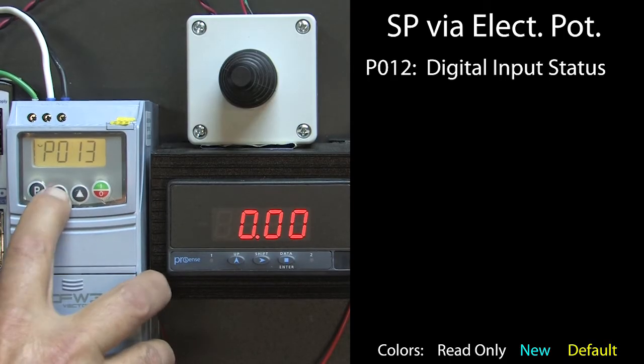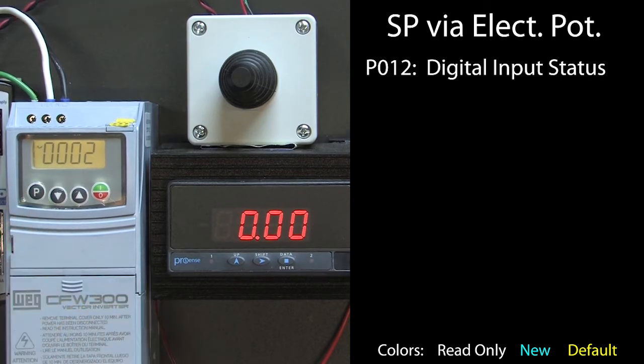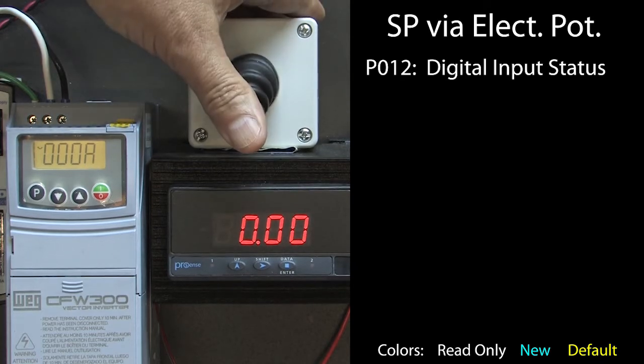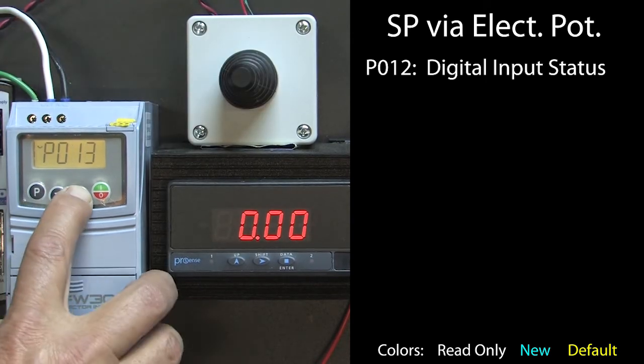Let's go to parameter 12, which tells us the status of the digital inputs. Push the joystick up, and yep, the 3rd bit lights up, giving us a 6. And if I push the stick down, the 4th bit goes active, which gives us a hexadecimal A. Perfect. We now know we wired it correctly.